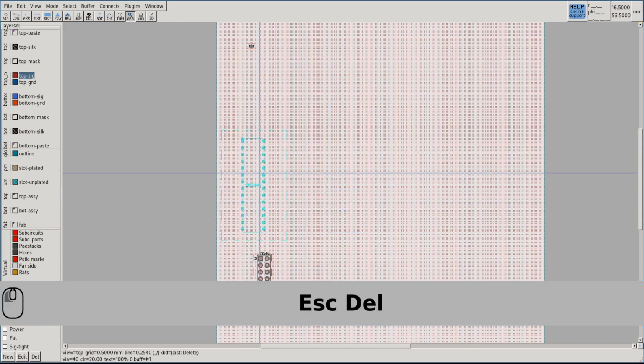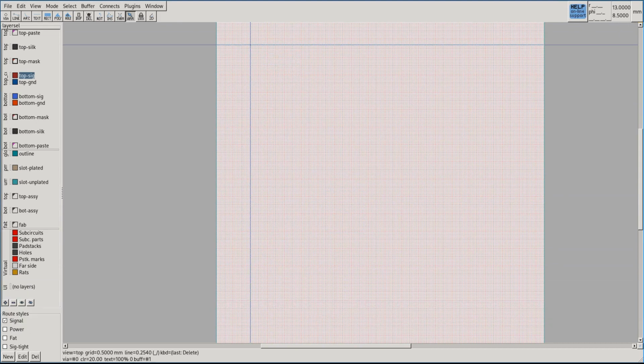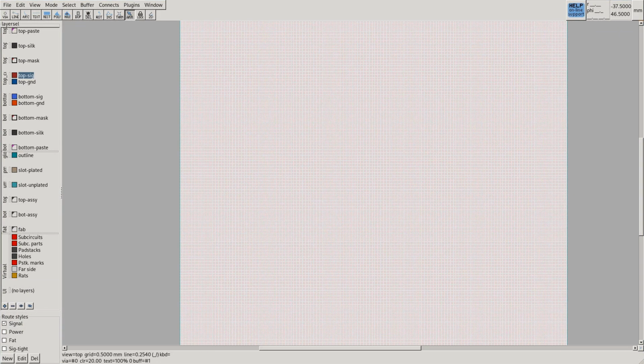Let's first remove the footprints because these are not part of my schematic. For that, just hover over it and press delete. And just before I import the schematic, I want to add a layer. So this is the layer stack up. Most common things are the top solder paste, then the top silk screen where you put your text and so on, top solder mask, which removes the mask so you can solder on the pads.